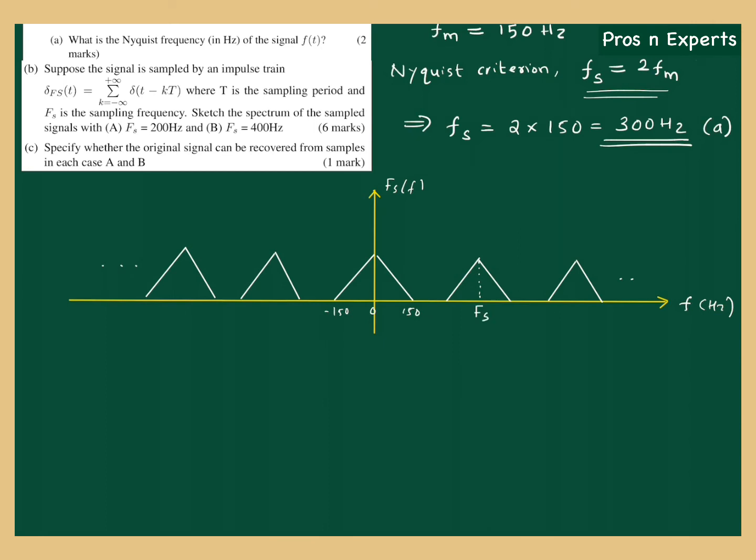This is the sampling frequency. Okay, you find this is the exact center of the message Fourier spectrum, and exactly after fs hertz, you get the next triangle, the next spectrum, and its middle. This center to this center distance will be fs, right? Now the second triangle has its middle at 2fs, then 3fs, and it continues likewise on the negative side: minus fs, minus 2fs, and so on. Okay, so this is an intuition about how the spectrum looks when it is sampled.